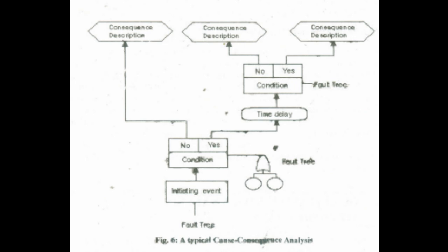3.5.2.3 Cause-Consequence Analysis. Cause-Consequence Analysis, CCA, is a blend of fault tree and event tree analysis. This technique combines cause analysis, described by fault trees, and consequence analysis, described by event trees, and hence deductive and inductive analysis is used. The purpose of CCA is to identify chains of events that can result in undesirable consequences, with the probabilities of the various events.